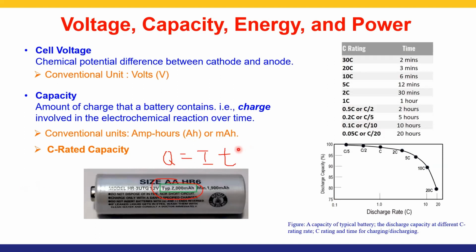Of course, this is not a standard unit. We say that the capacity is current rated, or C rated. So what is the meaning of C rated? If a battery has a high C, meaning we charge or discharge the battery very fast, the kinetics may not be able to follow and there could be a breakdown of the battery structures or the energy will be lost as well. So usually we will charge a lithium battery at 1C or discharge a lithium battery at 1C.